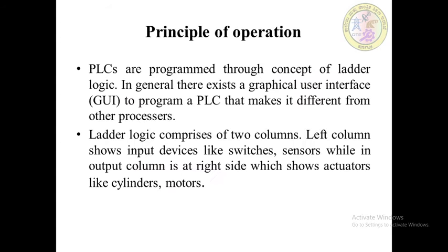And coming to this principle of operation, the PLCs are programmed through the concept of ladder logic. In general, there exists a graphical user interface, a GUI, to program a PLC, which makes it different from other processors. The ladder logic comprises two columns. The left column shows the input devices like switches and sensors, while the output column on the right side shows the actuators like cylinders and motors.